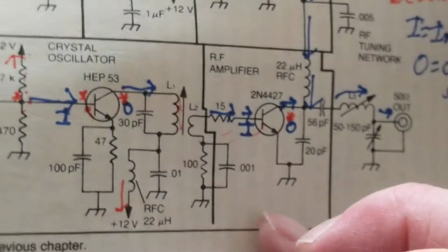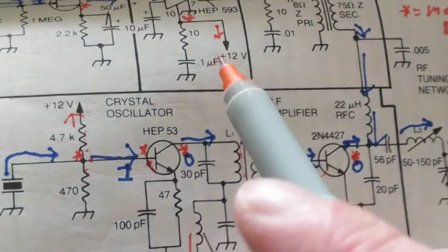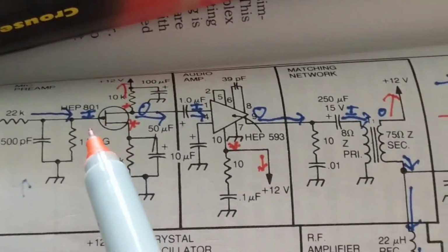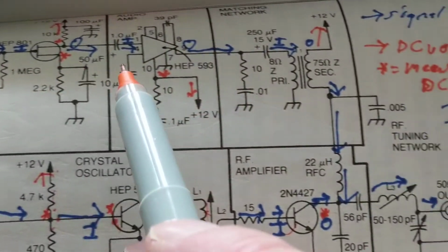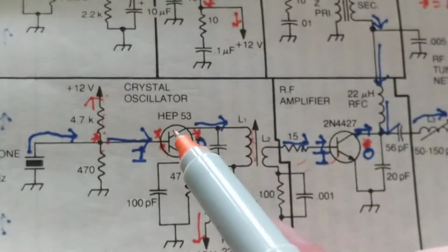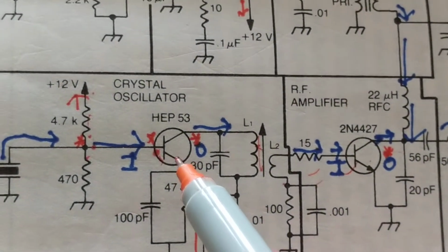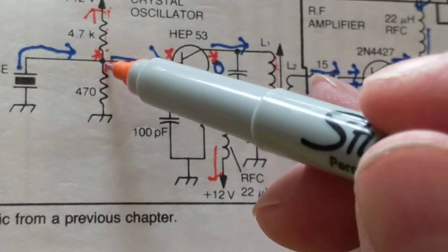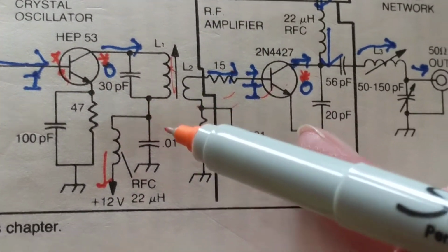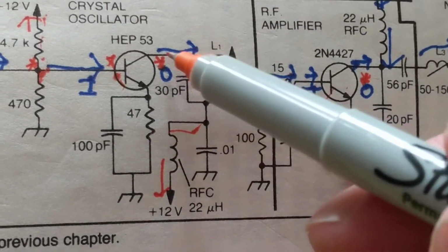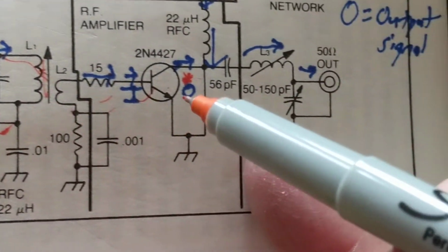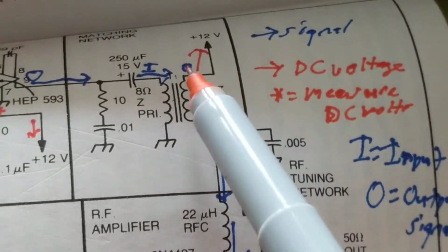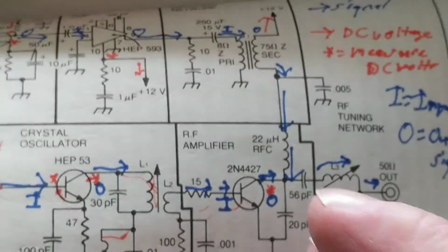So therefore, what I want to specify and stress, again, what are we looking for? AC signal? Then we follow inputs, outputs. Start from the left, work your way to the right. What do we want to measure? You can measure, obviously, the signals also, input, output. We want to measure DC voltage. You find the DC of it. Go to over here, measure this. Want to measure the DC? Go over here, measure this. Want the DC over here? Where does it come from? Follow it, and it comes over here. We can measure it over here. And that's how you approach it.